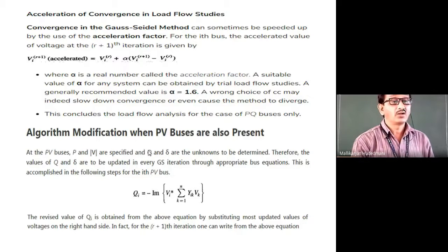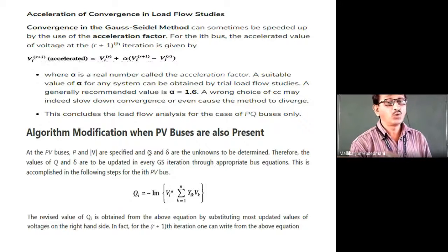If the Q value computed for a generator goes out of bounds, outside Q max or below Q min, then that generator cannot remain a generator in the process. In fact, it becomes a load. We call this bus switching. That is a test that has to be done first. Then we have to calculate the voltage of that particular generator bus and continue the subsequent process.